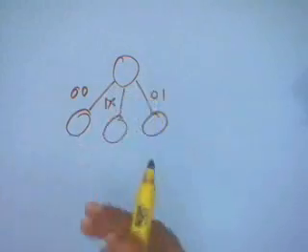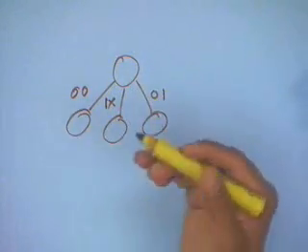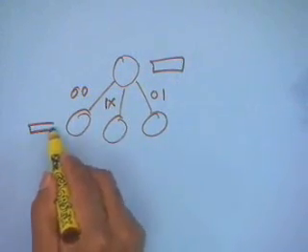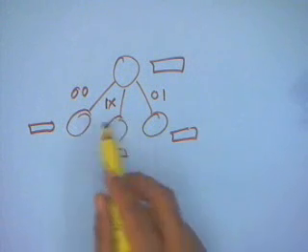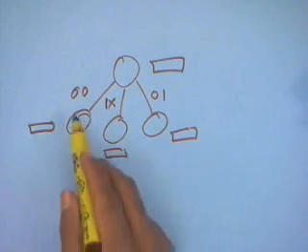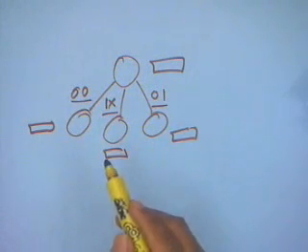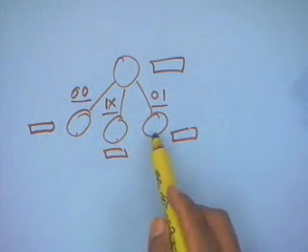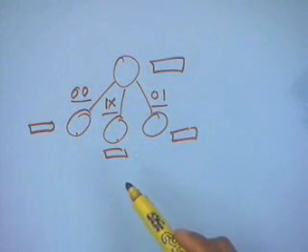If I now want to translate this in my microprogram, I am going to associate, let us say it is a Moore machine, the control is a Moore machine. I am associating some control signals with each of the states. What is the implication over here? The implication is, I am going to look at 2 bits of the input and either generate this set of control signals, this set, or this set, depending upon what these 2 bits are.